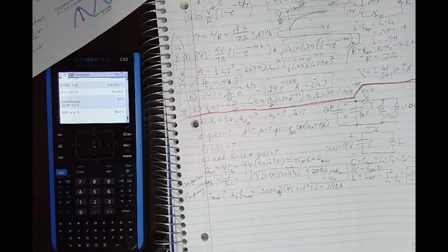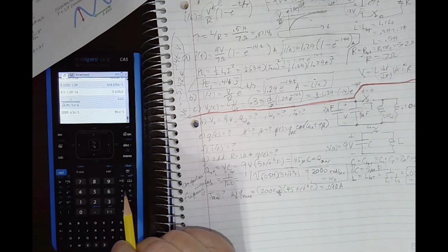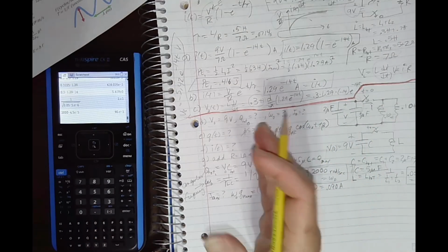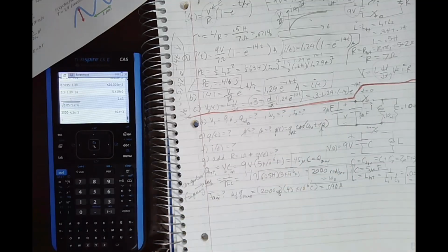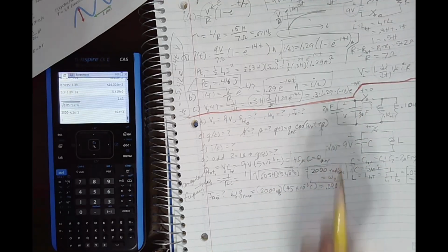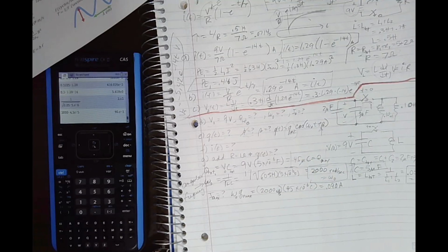How do we know this phase shift? We need some initial conditions, what's happening when we close the switch, so we have a t equals 0 point. That determines where we start in our cosine wave, because Q peak, which I call three different things, is just the coefficient of the cosine in the oscillation equation.